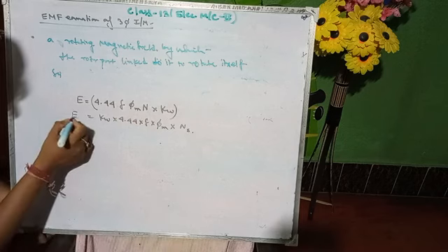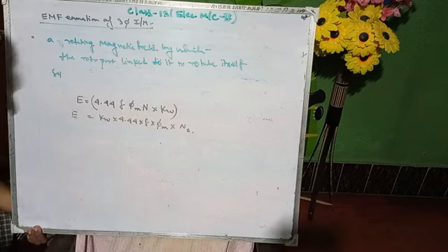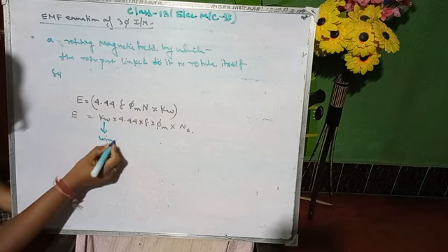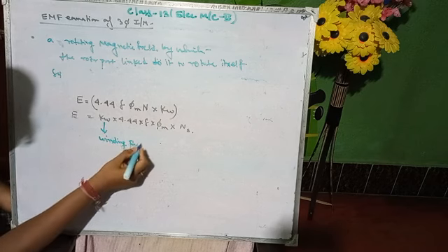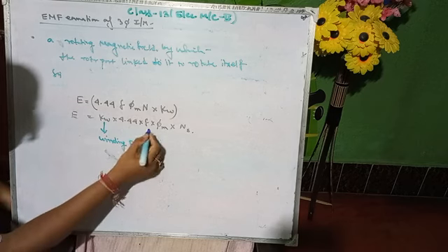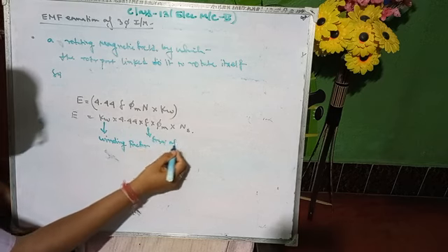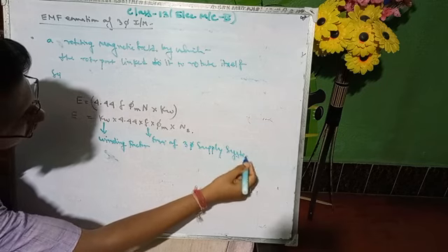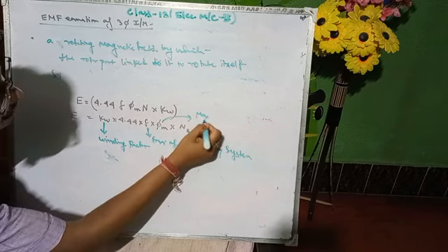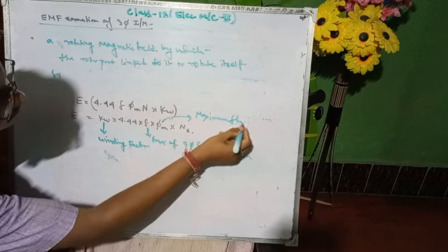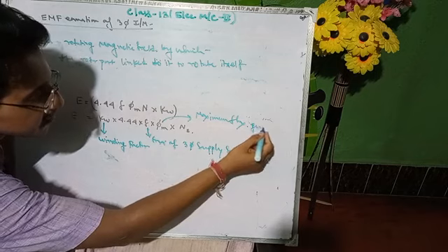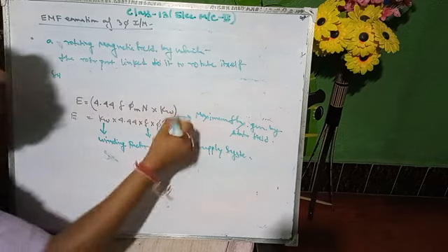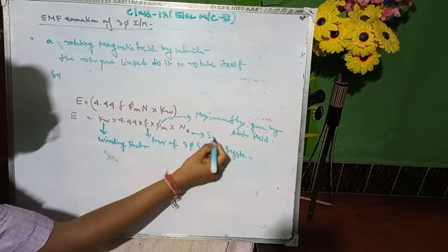Okay, so write where kW equals winding factor, F equals frequency of three-phase supply system, phi m equals maximum flux generated by stator field, that is peak of the flux. Okay, and Ns equals synchronous speed.